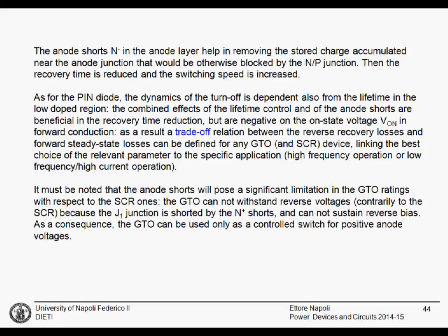There is also in this case a trade-off between reverse recovery and forward losses, and the optimal choice will depend on the application, the intended switching frequency, and the expected on-state voltage drop.